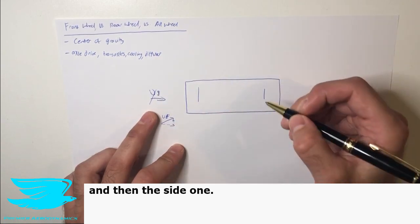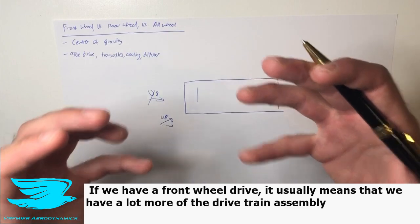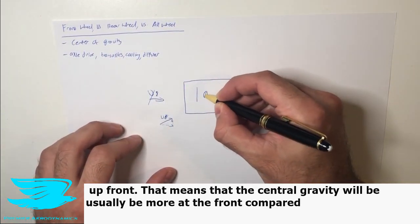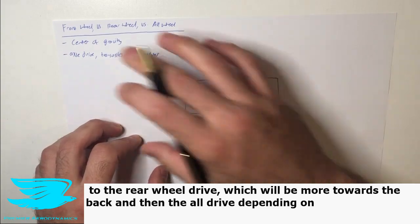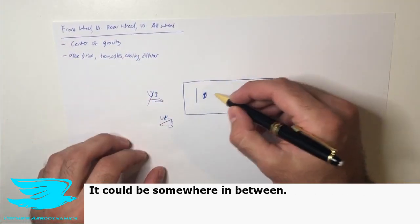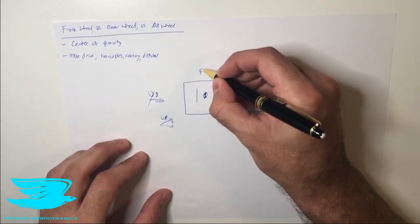one. And if we have a front wheel drive, it usually means that we have a lot more of the drivetrain assembly up front. That means that the center of gravity will usually be more at the front compared to the rear wheel drive, which will be more towards the back, and then the all-wheel drive, depending on how we have the transmission and the axles, etc., it could be somewhere in between.